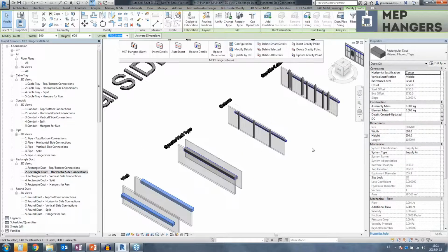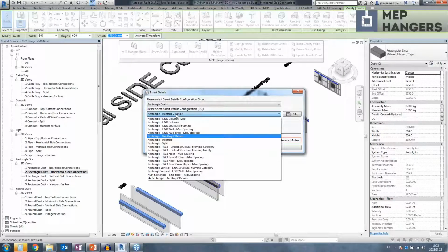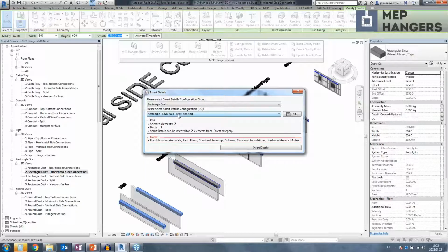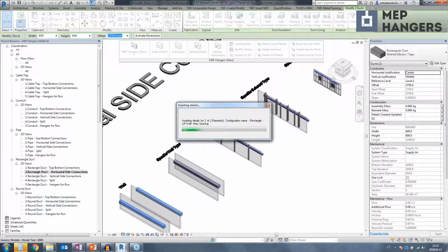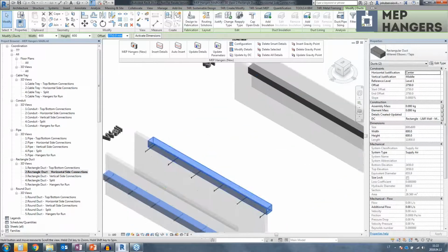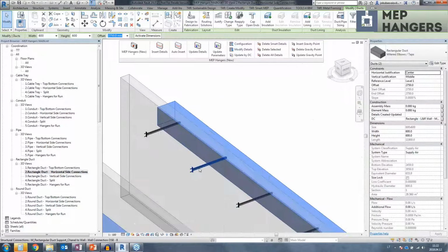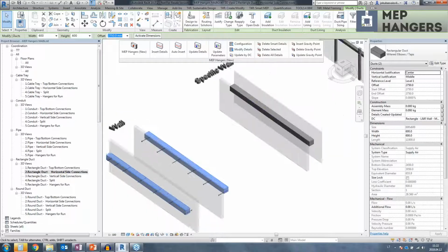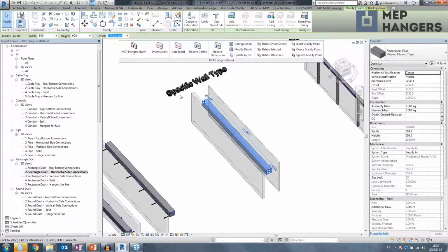I'm having supports that are mounted on walls, columns, or structural framings. So just the searching direction is changed. Right now I have to look for the walls on the left and right, and I just use maximum spacing. So the step of the hanger, like the layout, is the same. It is reading the size of the element. You can use any family you want. The same here, I have two walls, so the tool should decide where to connect.